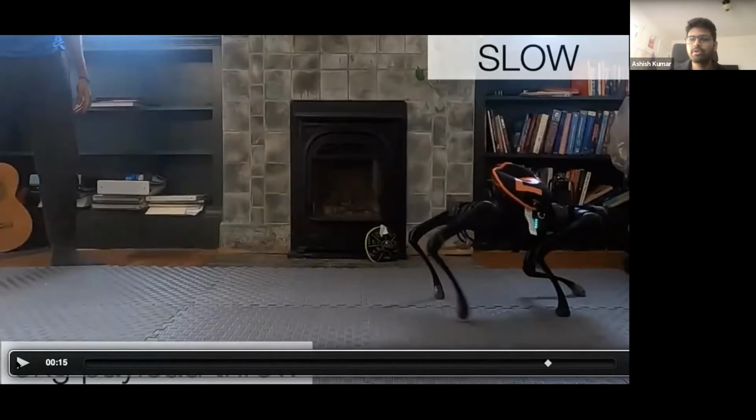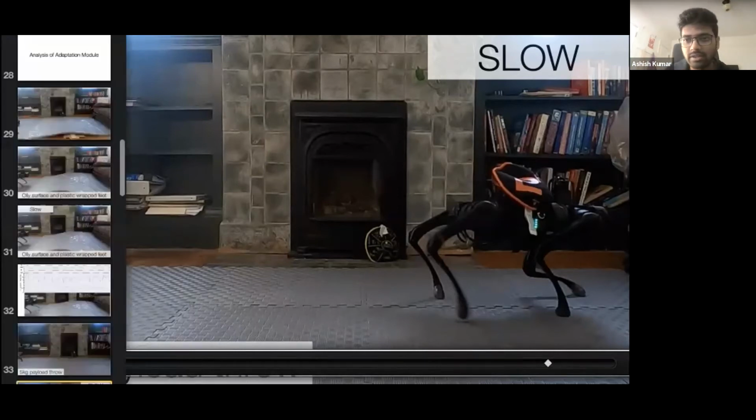So it needs some amount of history. So there's that inherent bottleneck on how fast it can adapt. And then there's a computational bottleneck: how fast can we run the network which is supposed to adapt? So we do see in the friction experiment that if the slip is very extreme, where the robot has to preempt the slip, so the robot should know that it is going to enter a slippery surface, in those cases it just falls. It is not able to react in the time frame.